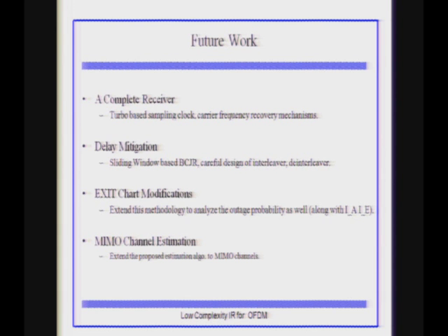When we talk only about BER, the problem with BER alone analysis, in my opinion, is that especially for MIMO cases, we do not worry about the outage. So it's fit for an AWGN kind of scenario, not for a fading channel case. All this BER analysis is good, but we need to show the outage probability along with this.